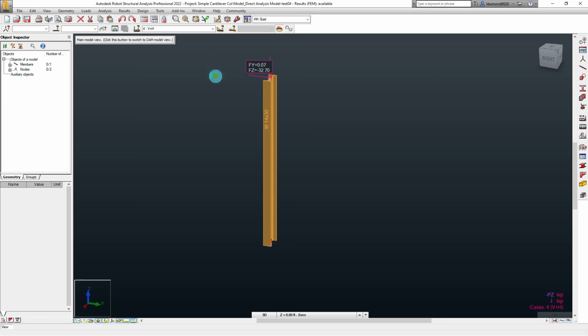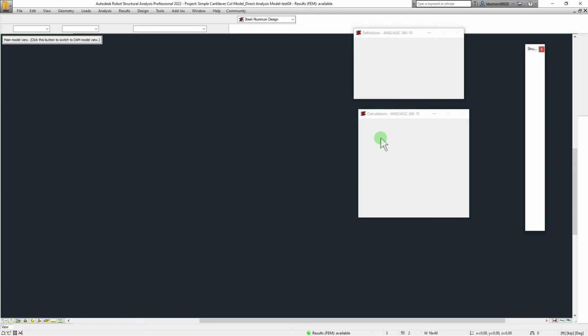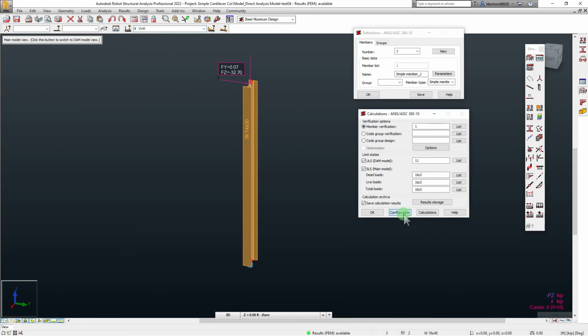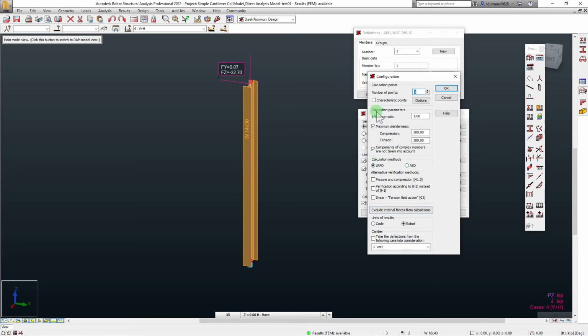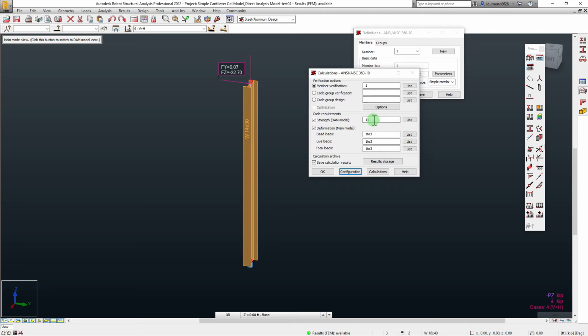Now, go ahead and go to Design. Show both our cases here. Check our configuration. See, that didn't take our allowable strength design, so we'll go ahead and save that here. I forgot to explain earlier that basically these are the combinations that it's checking. I'm not doing anything related to deformation right now as far as limit states, so I don't care about that.